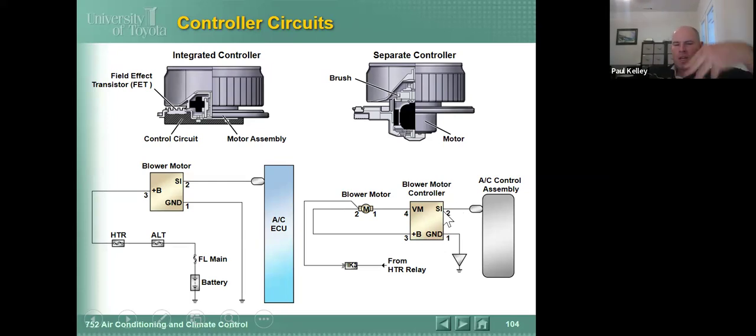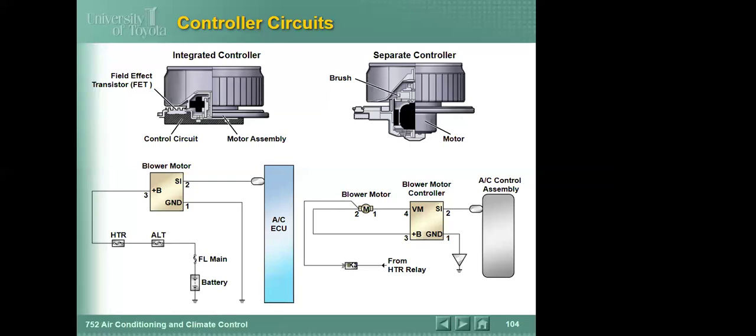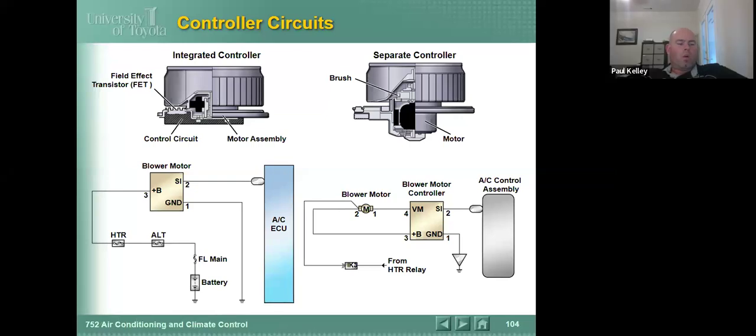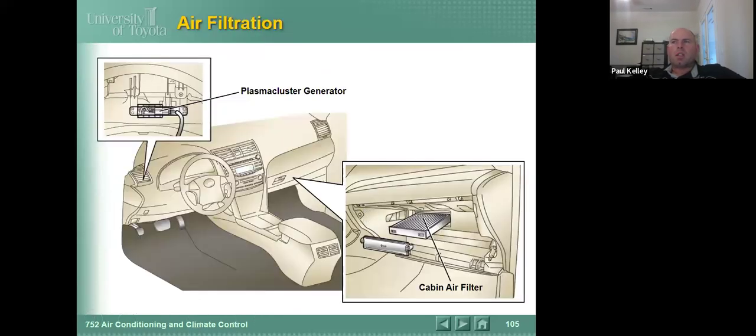And then duty cycle. Remind me how we check that. How we check that duty cycle? With a picoscope. You could go full pico if you want. Yeah, or you could use the Fluke 87 or 88V that has duty cycle function, and you could just get a number off it too. Yeah, you could do it a couple different ways. I'd probably use the meter because I can set it up quicker.